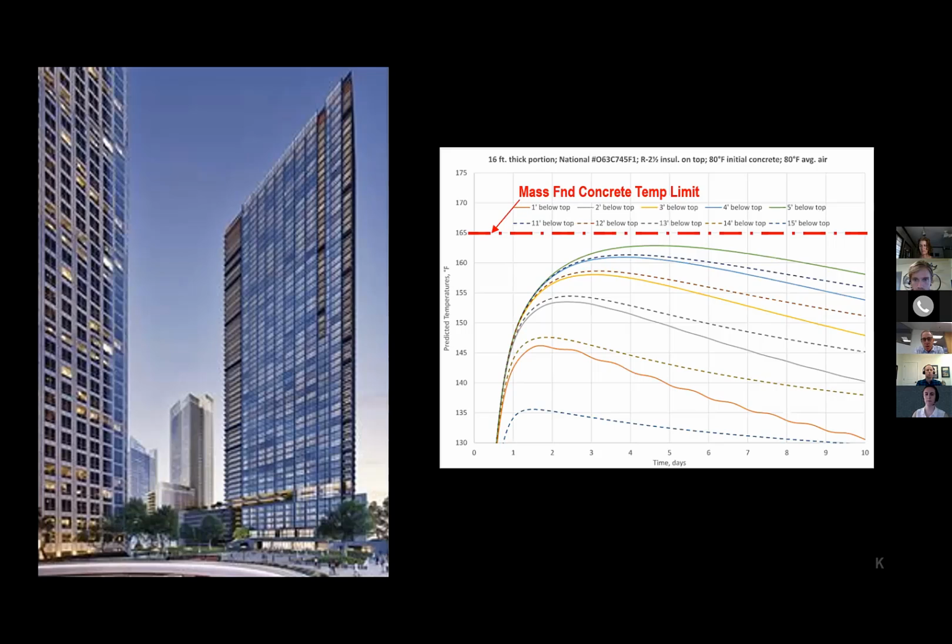That lowered the temperature of the rock by 15 to 20 degrees before it actually even got to the batch plant, and did a just-in-time delivery to put it in the mix and bring it to the site. A series of intervention strategies with those, coupled with some ice. The long story short, we were able to cut 2/3 of the cost out and greatly reduce the carbon footprint of what was going to be our mat foundation requirements to go in for this tower.